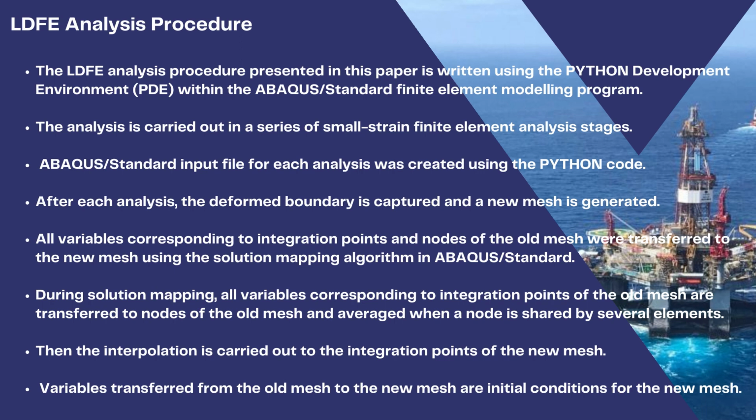Analysis is carried out in a series of small strain finite element analysis stages. Abaqus input file for each analysis was created using the Python code developed by me. After each analysis, the deformed boundary is captured and a new mesh is generated. All variables corresponding to integration points and nodes of the old mesh were transferred to the new mesh using the solution mapping algorithm in Abaqus.